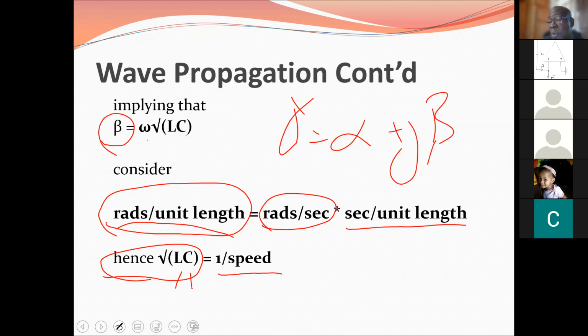Similarly, the insulation color may be different from what you will see going into Hope. Why? Because what you see around the neighborhood is set up to handle 24 kilovolts. What you see at Hope is set up to deal with 69 kV. And what you see down at the Park is set up to handle up to 138 kV. And insulation is expensive, so you're not going to buy 138 and use it at 24.